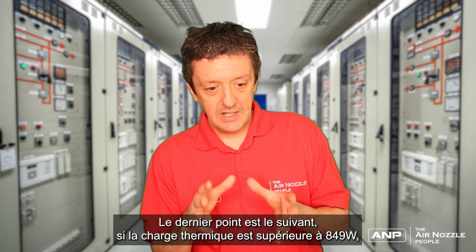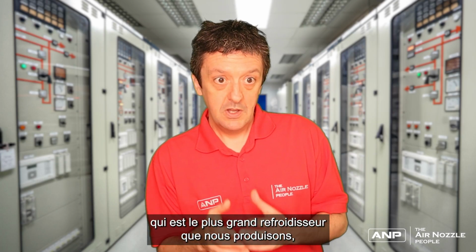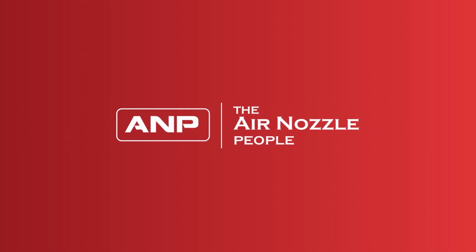Final point is, if the heat load is more than 849 watts, which is the biggest cooler that we produce, you can use multiple coolers in one cabinet. There's no reason why you can't do that, so that can cope with larger heat loads.